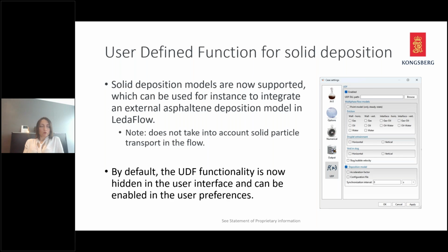Please note that we have decided in LedaFlow 2.10 to hide the UDF functionality by default. Before it was shown, as you can see here on this screenshot. So it was shown by default, but this is a quite advanced functionality. So we have decided to disable it by default, and it's possible to make it visible again through the user preferences.